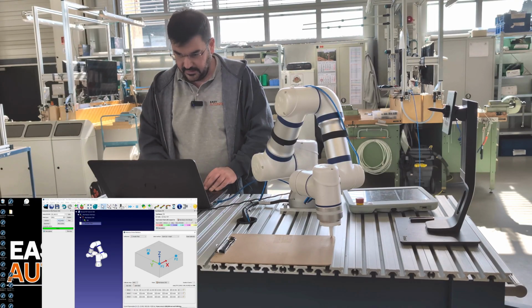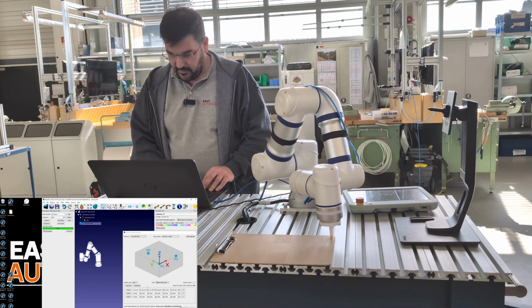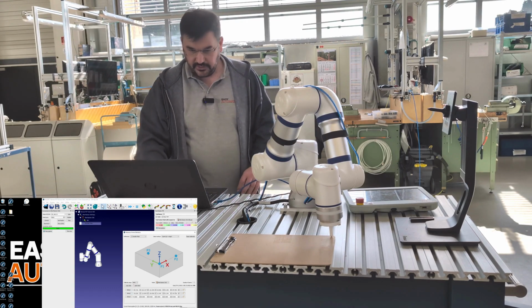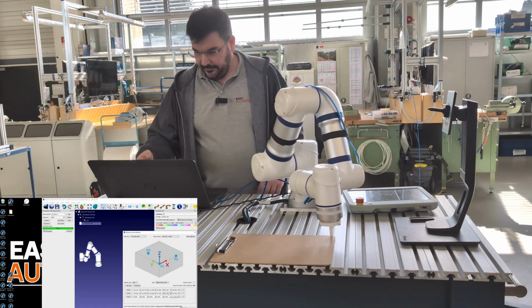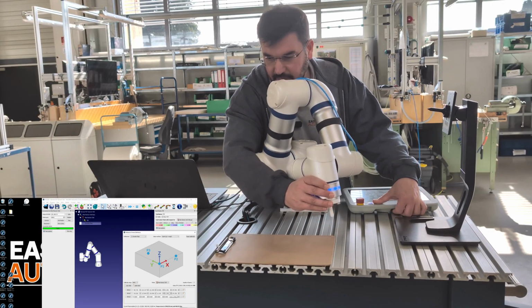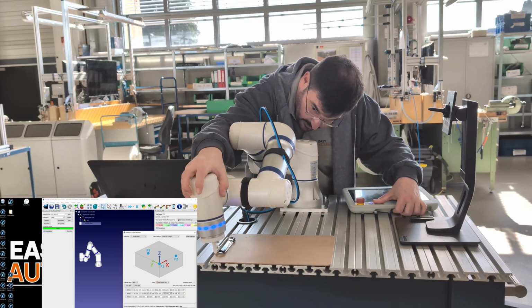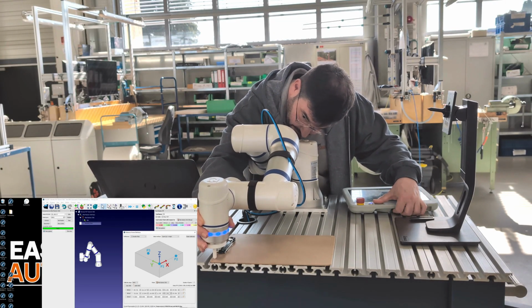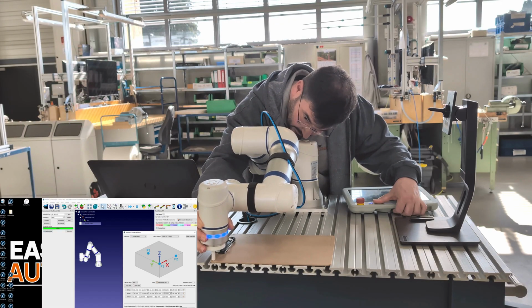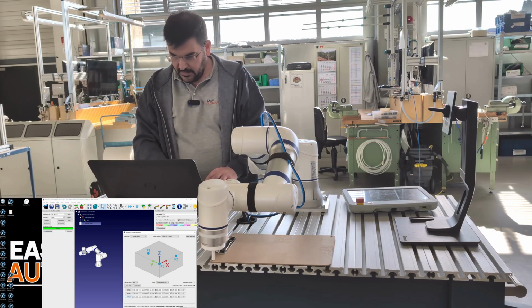Right now, I just hit get position. You can see on the screen that the robot position coordinates were read out one by one. And I just hit get P2. And here you can find the joint values for this. So the third one is the Y. I could use any point on the surface, but I'm going to define the Y position, because this is how we normally use it and recommend it. So, we just hit get position. It's done. And get P3.